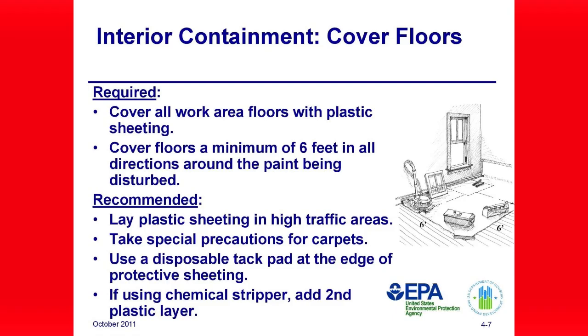You may find that using a HEPA vacuum to clean off shoes and clothing is necessary in controlling carry-away dust when personnel leave the work area. This is called dry decon and works very well when utilized.